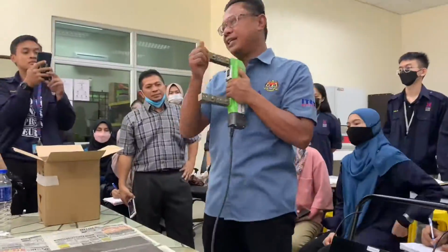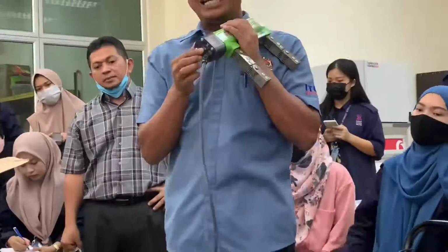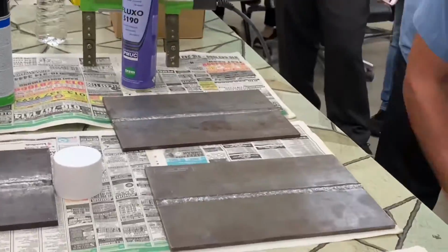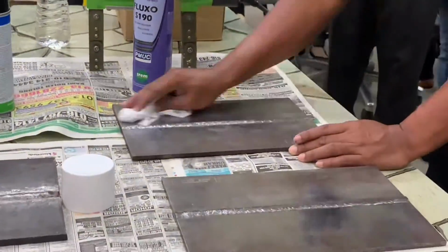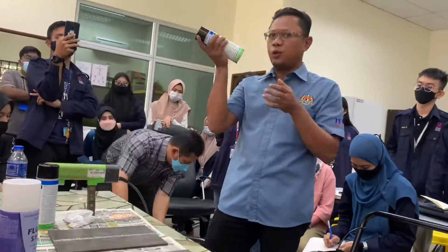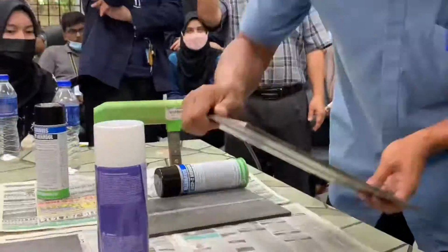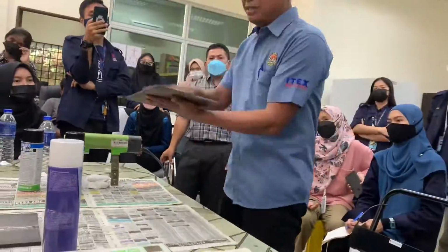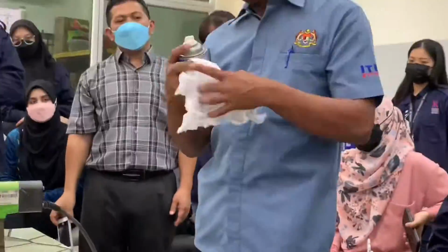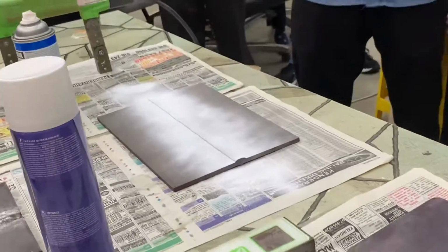Magnetic particle inspection, often known as magnetic testing, is a non-destructive inspection procedure that detects linear faults near the surface of ferromagnetic materials. It is mostly used for surface inspection. Magnetic testing is a highly successful method for locating surface-breaking and minor subsurface defects in magnetic materials, such as cracking, porosity, absence of sidewall fusion in welds, and so on.